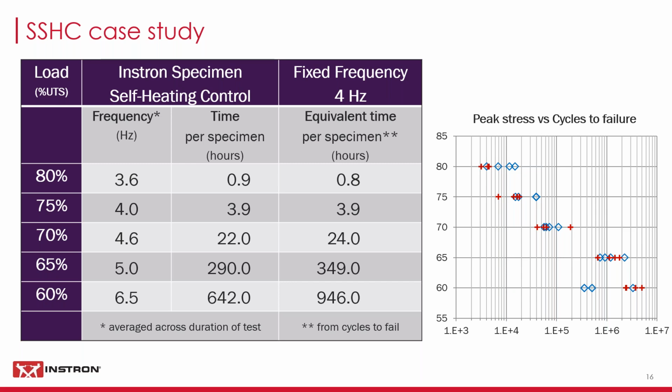Perfect. Right. Thank you for that. And then there's another one here, which is saying, are sample fixtures like a split capstan grip good for testing fatigue on non-tabbed single ply continuous fiber composites that are flexible enough to bend around the grip?